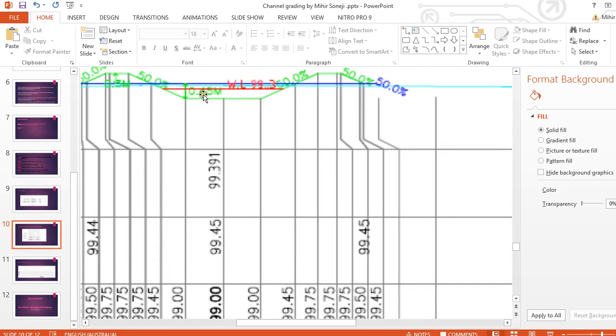So the total is 0.75 deep for my given quantity of flow. For the natural ground surface, which you can see here is a sand line, I then raised my surface and compacted it by creating one more pad surface. From that surface I created 0.45 deep, excavated the ground and filled both banks in here, with 2 in 1 side slopes.